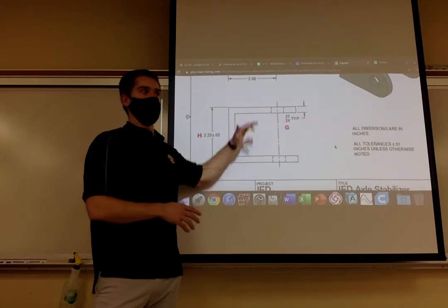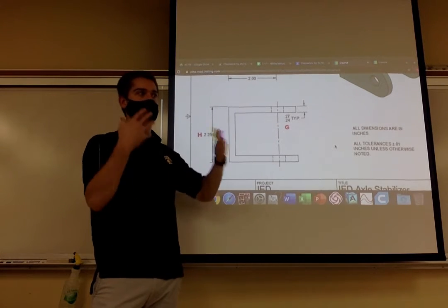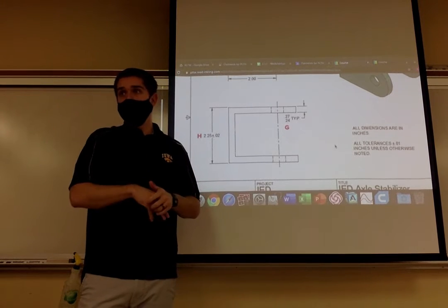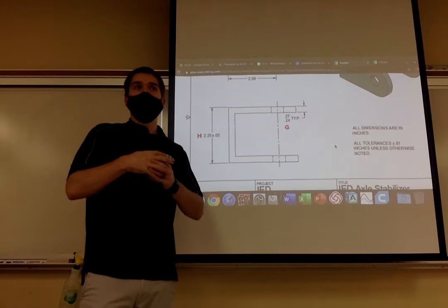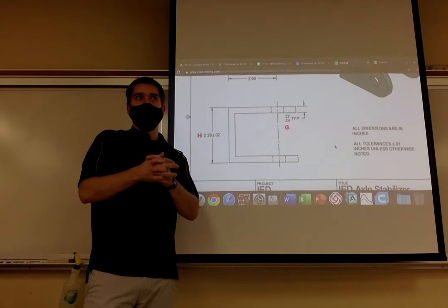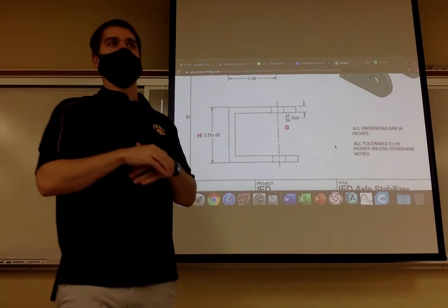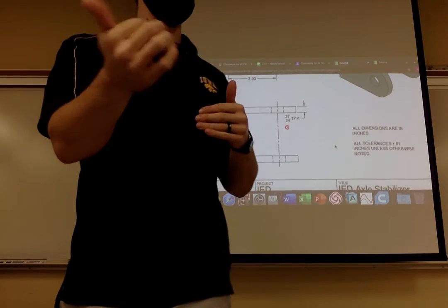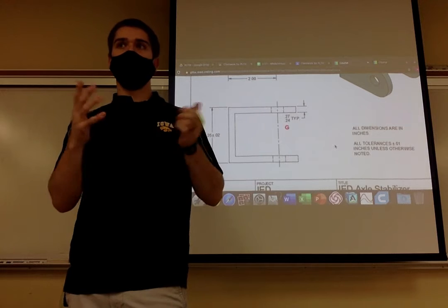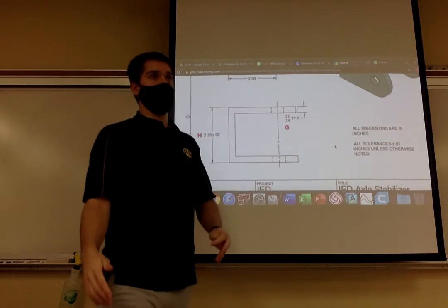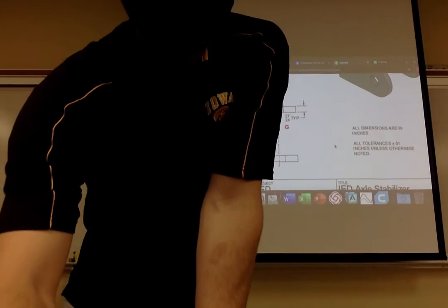This is just to make sure that you can identify the types of tolerances, because eventually you're going to have to use them. You're going to have to say, I need to tolerance my part. What kind of tolerance do I want and why? Sometimes you might think it can't be larger than this, so I'm going to use a unilateral. If I don't really care either way, I'm going to give bilateral. Sometimes you might choose to list it as a limit, right?